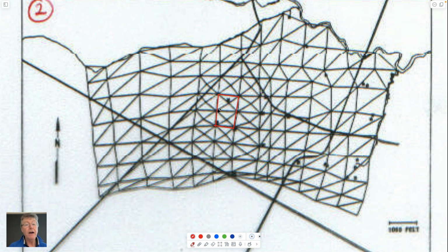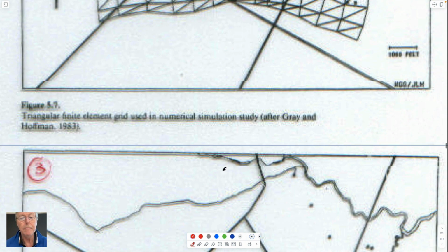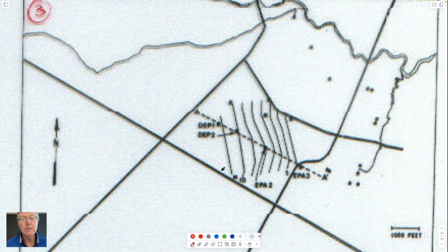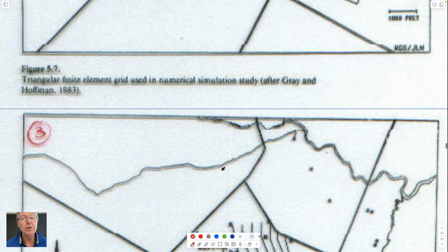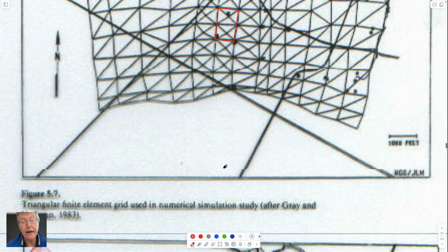Each of these finite elements would account for the amount of fluid that came in through one face and the amount going out through the other faces or sides, and do the accounting to be able to solve a big system of linear equations to do that. And so you'd set up a model to do that, of which there are many available. You would want to calibrate that model so that it actually returns the behavior you have.